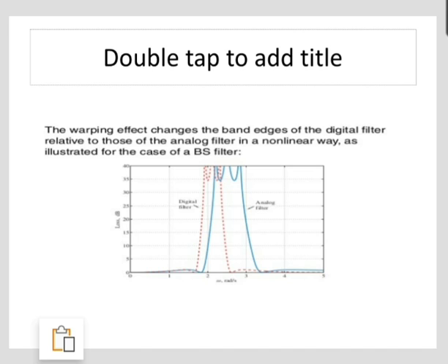This effect compresses the magnitude and the phase response. This effect is called the warping effect. So pre-warp the desired digital frequency and substitute that into the transformed digital filter function.